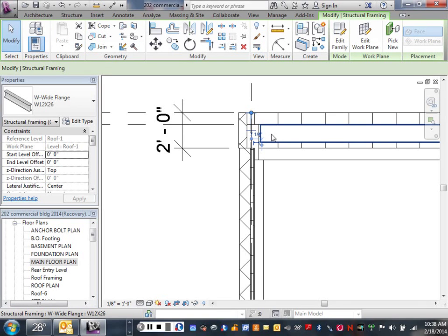So that decking comes across and sits on the beam, bar joist, bar joist, bar joist, right? So the beams that are on the end here then should be 2.5 inches taller. So the starting level of that beam should be, instead of a minus 8, a minus 5.5.